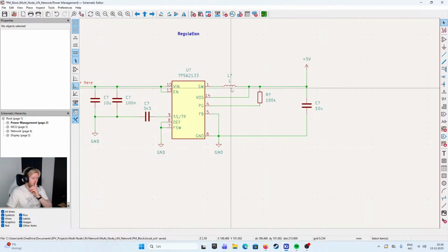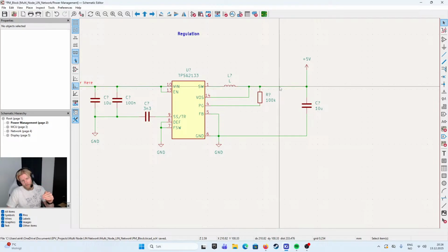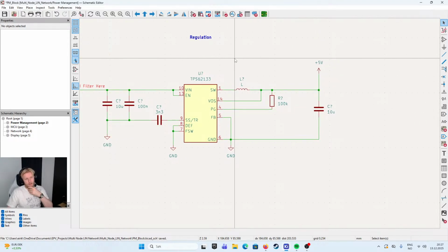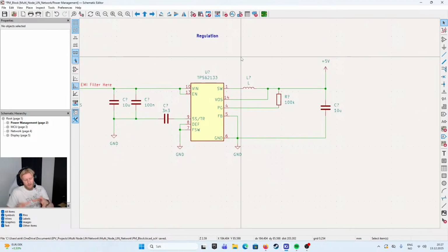For example, selection of the inductor is important in order to set the acceptable ripple on the output. Also then the filtering of capacitors, etc. And I would just like to make a structured way to keep track of what I'm doing, so I can look back and make it simpler the next time.